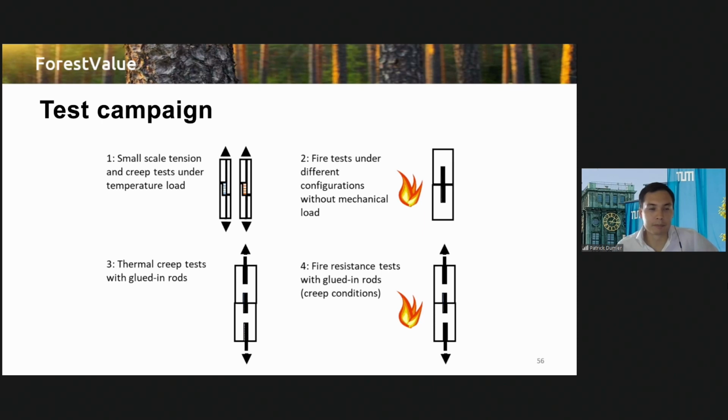Therefore, we conducted a test campaign consisting of four different tests. The first were small-scale tests in tension and creep under temperature loads. The second were fire tests with different designs of the specimens and without mechanical loading under the standard fire curve. The third were creep tests with specimens with glued-in rods, but with temperature load. And the fourth test series is the same as test series 3, but under the standard fire curve.